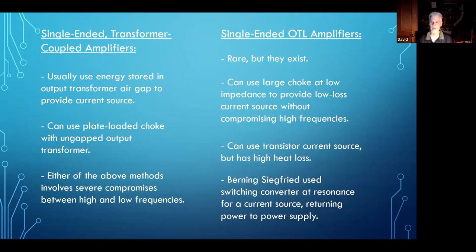It's not being crossed over to another tube, because the current source is high impedance and the tube is low impedance, so the tube is going to dominate the entire waveform. So it really does meet the criteria of a single-ended amplifier, having one tube control the entire waveform rather than half controlled by one tube and half by another.